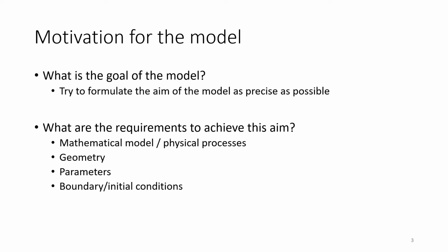Do you want to have, for example, planning observation wells? Because how is the flow velocity? Is the flow velocity high? I need to model a larger domain because the tracer is transported quicker over longer distances in the same amount of time. Right? So you see, once you define your goal and your project, there are subsequent questions you need to ask yourself, or you need to ask your client, to design a suitable model.